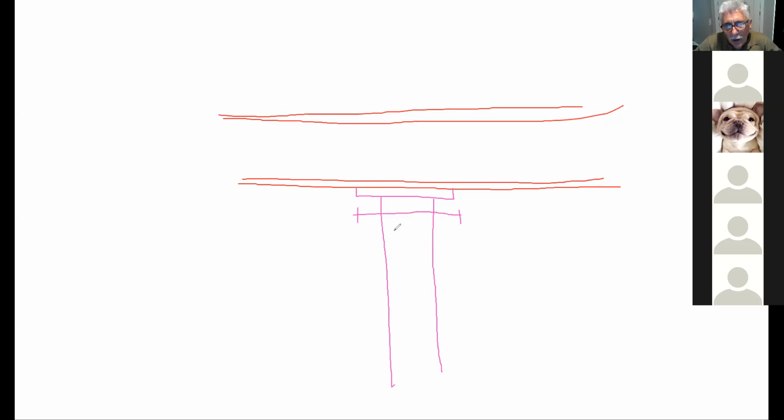This length here, I don't know what you have, but let's say if your column is 176, this should be in the order of about 240. I don't know. But you understand this length here, L here? Well, that's your N value. So in other words, whatever you design your base plate for, use the same dimension for your cap plate, because it's going to be a square one, and therefore this is your N value in the web crippling, the length of bearing.